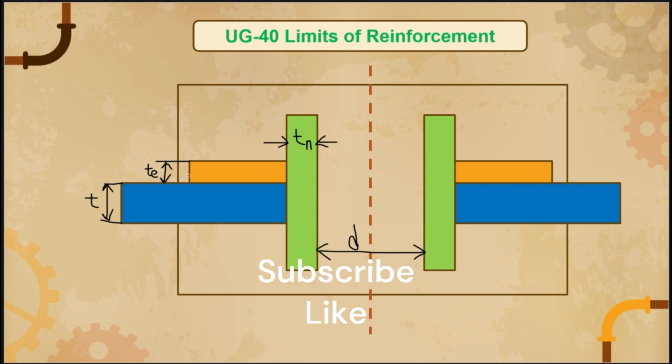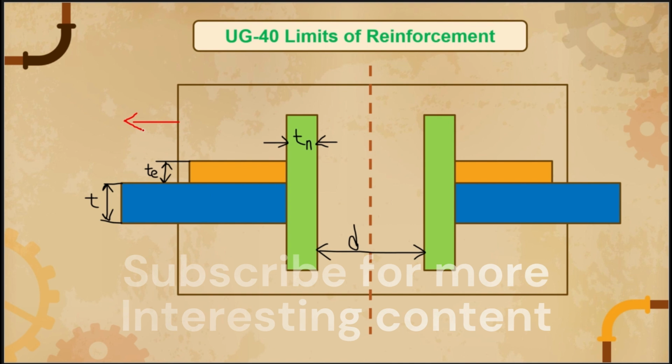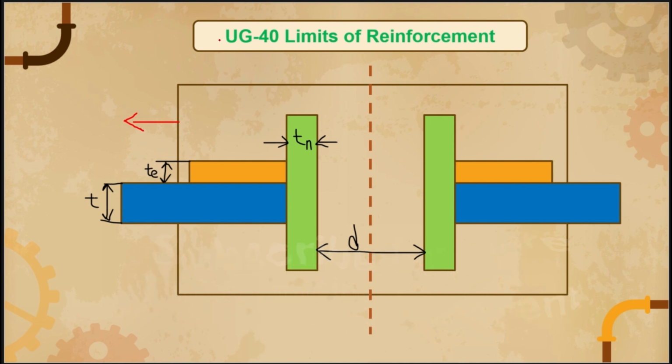Whatever reinforcement pads you provide must be within this rectangular box only. If you provide them outside this rectangular box, they are not considered as reinforcement, because these are the boundaries within which additional material must be located to compensate for the material removed for the opening, guys. We need to select the maximum dimension in both scenarios: one is normal to the vessel and the other is parallel to the vessel wall.